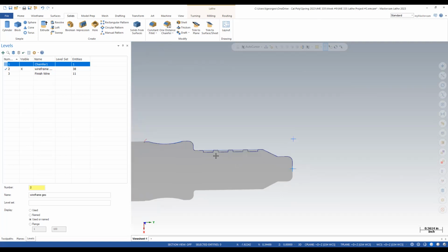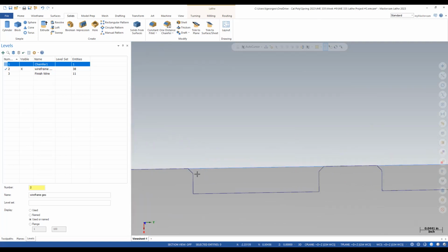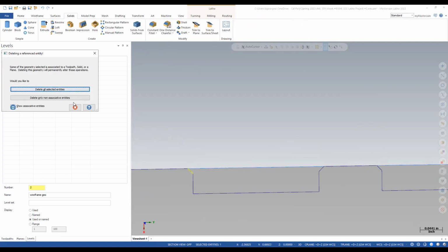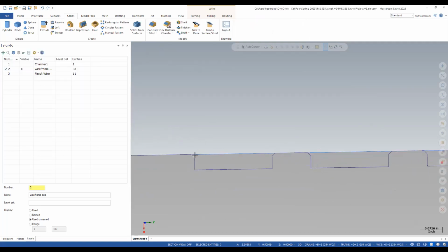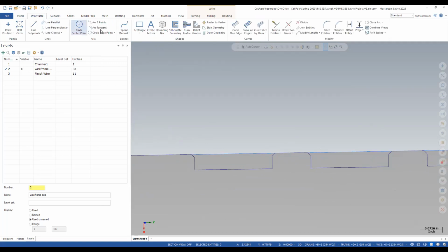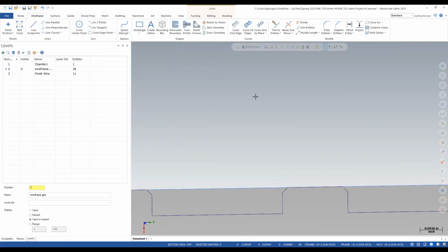So check this out. If you had a sharp corner, I don't want to start deleting that, but if you have a sharp corner, the wireframe and this chamfer tool does it for you right here. So don't make your model have the chamfer on it. Just put it on the actual wireframe right there. 10 thou chamfers. Did I just solve your problem? Yeah, somewhat. Cool.